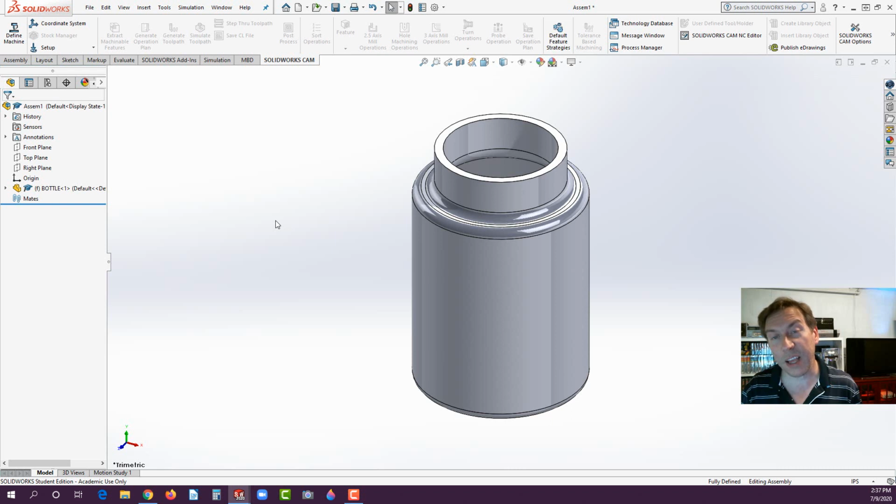at the origin automatically when you hit that green check after you've selected it. If you click and drop it out there, that's fine too. Like I said in exercise 5 a couple weeks ago, if you hit the green check, it's always dropping your part's origin onto the origin of the assembly. That's a good strategy for modeling inside the assembly. Not all companies do that. Anyhow, all right, let's bring in the next part.